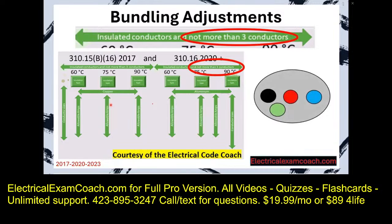Let's imagine that we have a piece of conduit here, and we pulled in a black, red, blue, and an equipment grounding conductor. What this table is saying is that those ampacity values listed down below in this table are true as long as you have not more than 3 current carrying conductors in a cable, pipe, or raceway. If you do have more than that, then we have to do what's called a bundling adjustment.